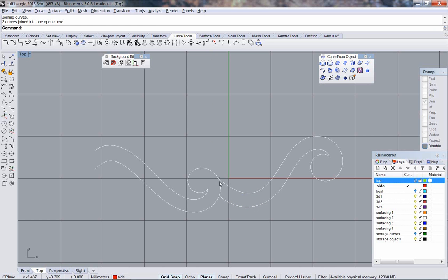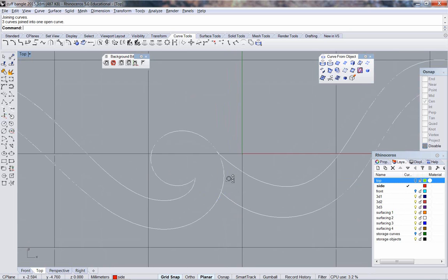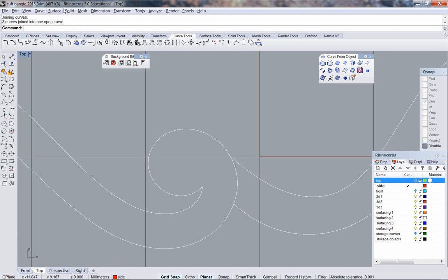Alright, I don't want these to end right at this, I want an overlap to take place, so I'll engineer that right now. Extend by arc to point. And I'll just bring it back in here. I'll do a curve perpendicular and snap. Excuse me. F enter for from first point. Pull that down.